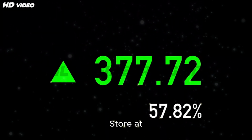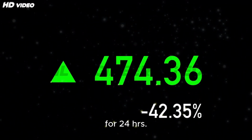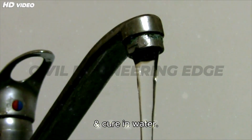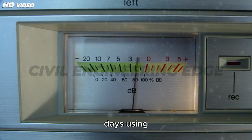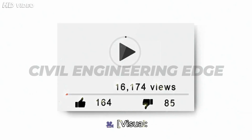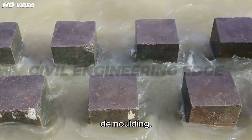5. Store at 27 degrees Celsius, 90% humidity for 24 hours. 6. Demold and cure in water. 7. Test at 3, 7, and 28 days using a compression testing machine, CTM. Visual: cube casting, demolding, testing in CTM.